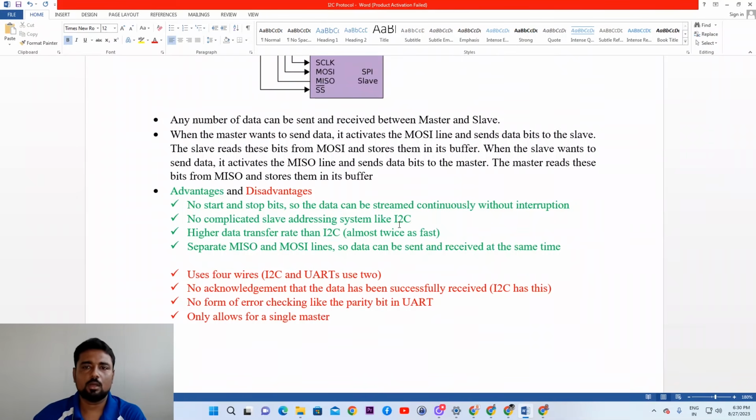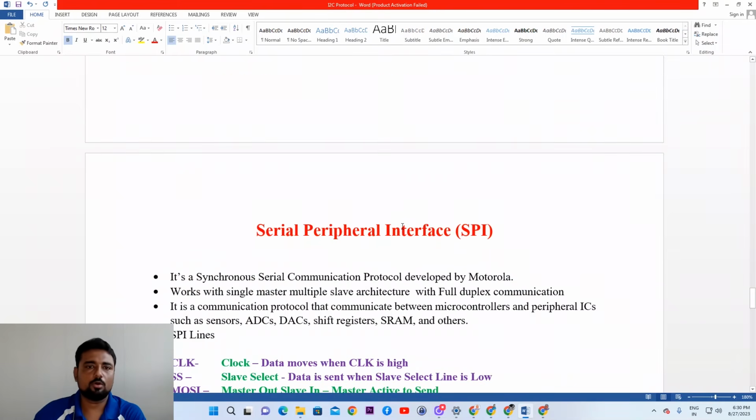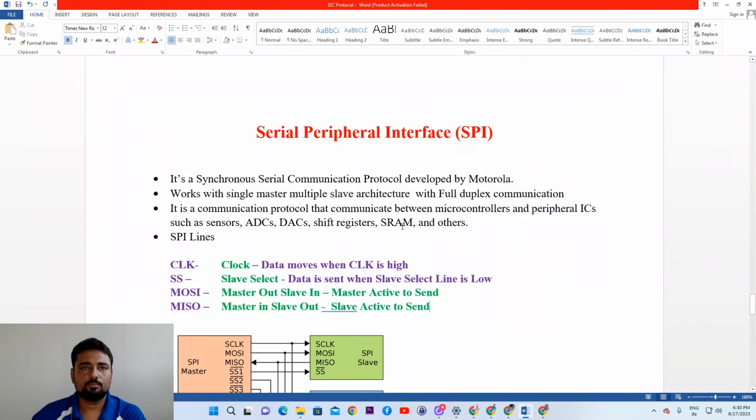So this is the information about SPI and I2C. With this, we tried to get the simulation, but the SPI protocol is not accepted by Tinkercad. Because in Tinkercad, you remember that in the I2C protocol we wrote Wire.h. Wire.h activates the protocol for I2C. In a real Arduino, if you want to use SPI, you have to use SPI.h. It will activate the SPI protocol. But in Tinkercad it's not supported, so we are not going to do the simulation for this one.